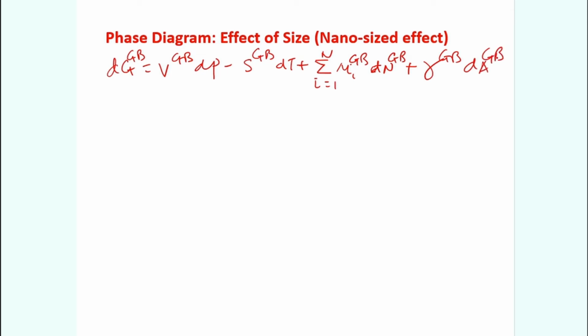Right. So this is G, GB is superscript. GB is always a superscript because it's talking about grain boundaries. Right. Now, when you have such kinds of structures, when you have grains and grain boundaries, just now I showed you, two other conditions are to be met also. This is a system, right? Grains and grain boundaries. Obviously, the first condition to be met is mu i GB must be equal to mu i grain, or rather bulk.